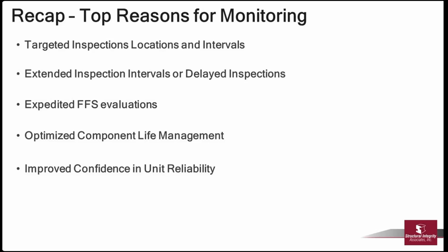There are ultrasonic sensors that you could put on the water line to detect that there's flow going through it. That's one type of ultrasonic sensor for spray water. There's also a spray-on transducer, which you can think of like an ultrasonic thickness meter. When I say spray on, you're actually applying a piezoelectric paint to the piping that you can connect wires to, and you can actively monitor thickness during real-time operation. So they're somewhat different.